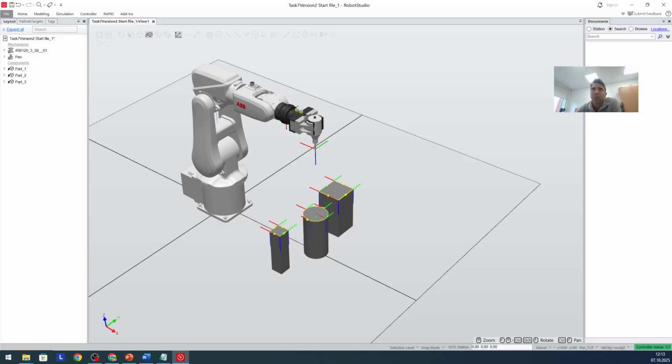This is all what it does, but I will modify the rapid so that I can determine by the teach pendant, the operator can tell which one of the shapes the robot has to, for example, weld, and how many times, because sometimes some operations need to be repeated like 2 times, 5 times, 3 times.